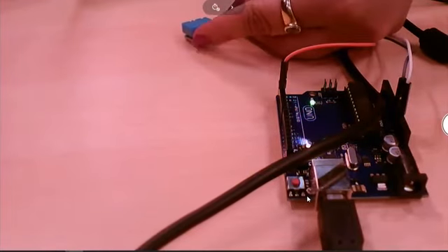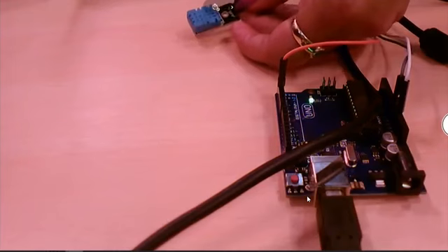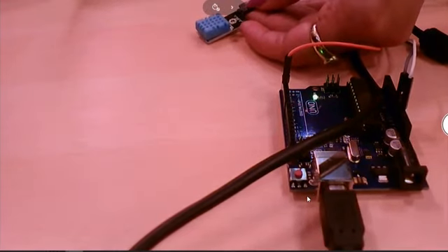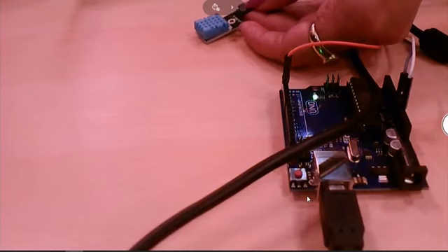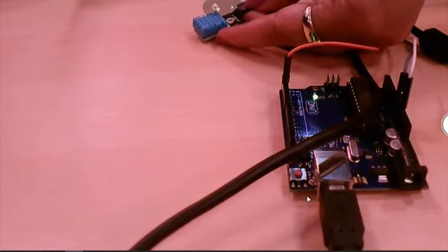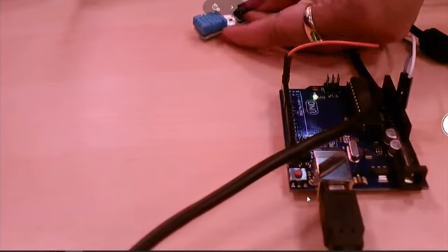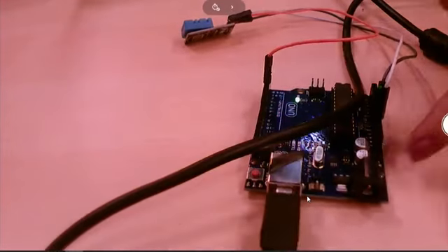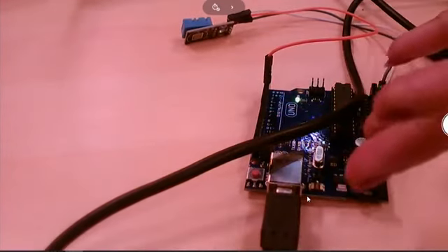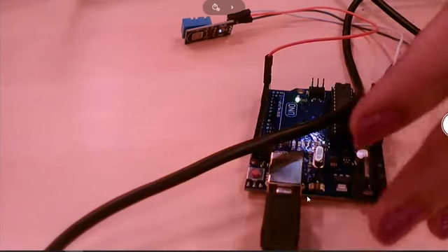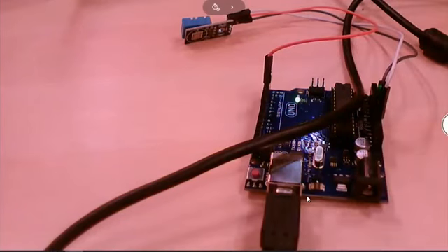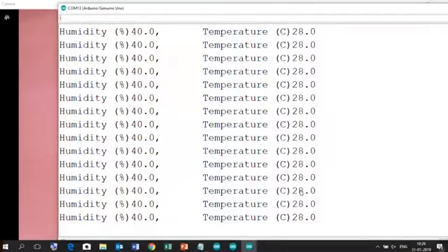This DHT11 sensor is really useful for the kind of POCs if you want to develop, where you want to capture temperature and humidity, and according to the range of temperatures that you are looking for your POC, you can actuate something, probably again the LED or any other action you want to take on the transducer output side as the actuation, that can be taken care of. So, this was a sample example understanding DHT11 for capturing temperature and humidity, and I tried to display that here on the serial monitor.